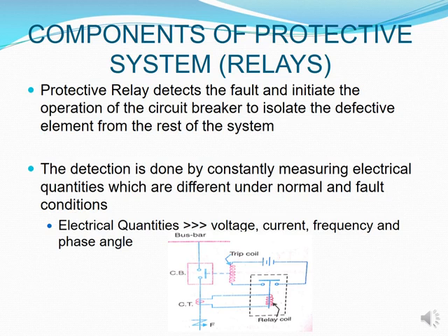And if you can see at the bottom, it says now there was a fault that was introduced into the system. So the CT has been reading continuously and there has been nothing happening. All of a sudden, your system gets a fault, and now your CT needs to pick up that fault, and it sends that there is now an abnormal current that I'm receiving in my system.